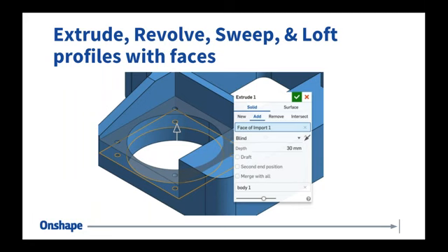The important thing to stress is, again, it's one of the tools that almost no one thinks of when they import a model, but works really well in a number of different situations. Right. So important thing to stress, again, it's not just about the 4 direct editing tools that you see in the toolbar, but also some other features that may work as well. Right. So extrude, revolve, sweep, loft, all work just fine with face selections.